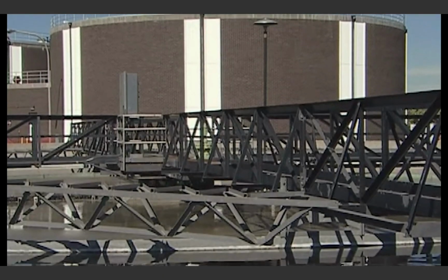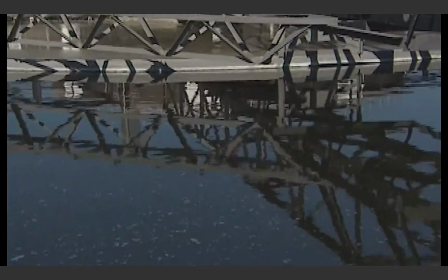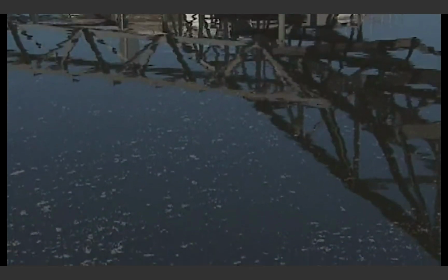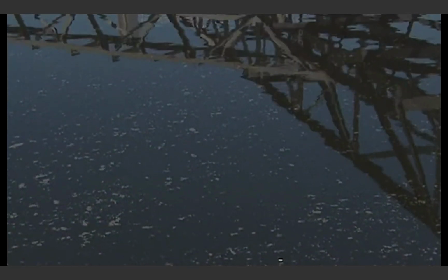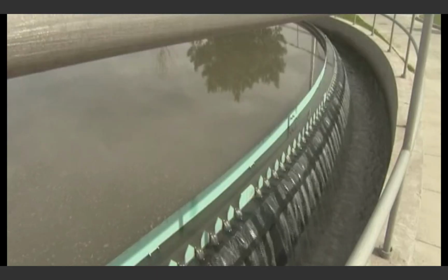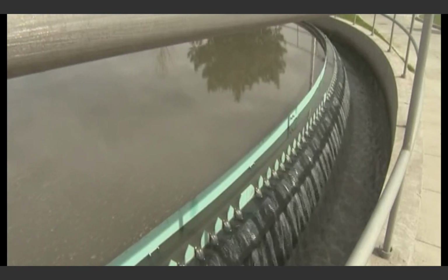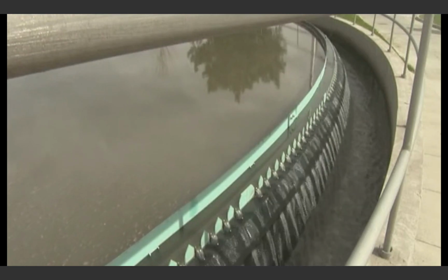The wastewater enters the clarifier, the speed of the incoming water is slowed, and the water evenly distributes around the tank. The point is to introduce the wastewater into the clarifier as quietly as possible. The higher the flow rate, the greater the turbidity and the greater the solids flowing over the effluent weir, rather than settling out as solids.